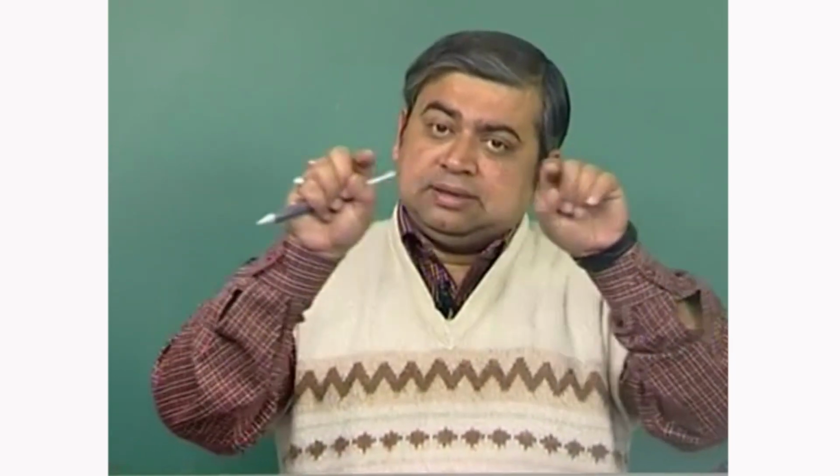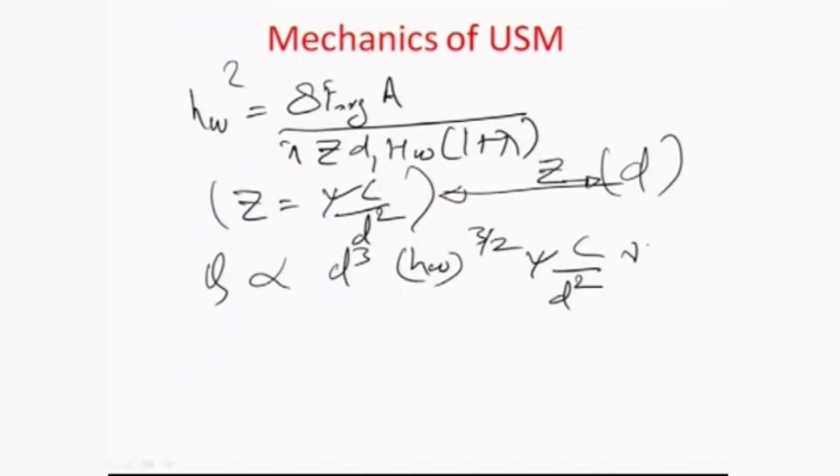So, that is why the z value does not alter; the z value is still inversely proportional to the square of the diameter, okay, because that is ultimately the determinant of what would be the grain to grain spacing. The average diameter of the grain is the determinant of the grain to grain spacing between the tool surface and the workpiece surface, assuming a fixed tool area. So, therefore, this expression here becomes conveniently changed and Q becomes conveniently proportional to the average grain diameter d, which is in consonance with of course the experimental observation.